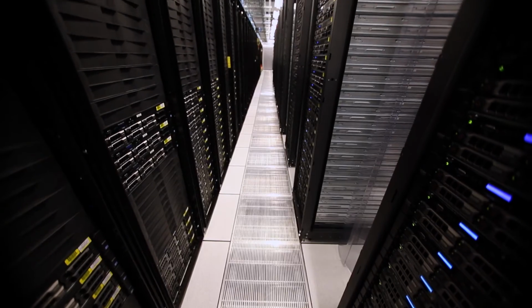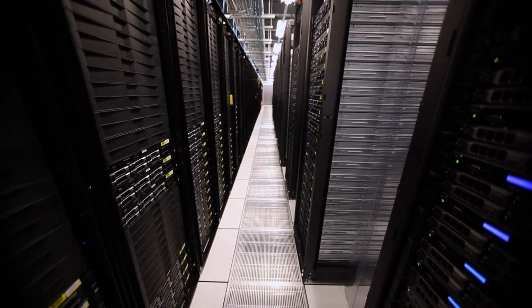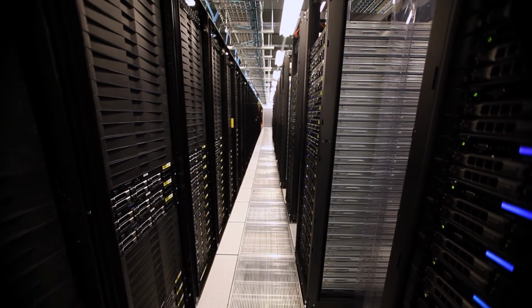With a more traditional data center, the architecture of the space generally revolves around what are called CRAC units, computer room cooling units, and they would supply air via a raised floor void, and then the air would be supplied into cold aisles via floor grills.